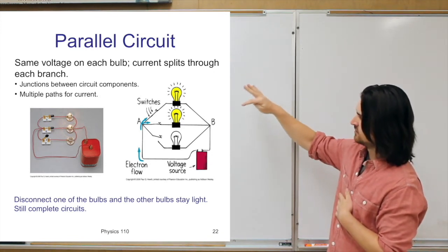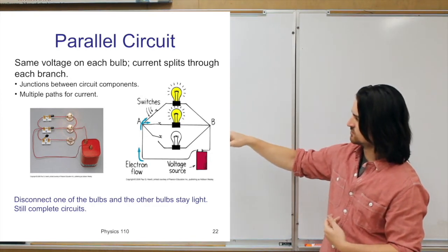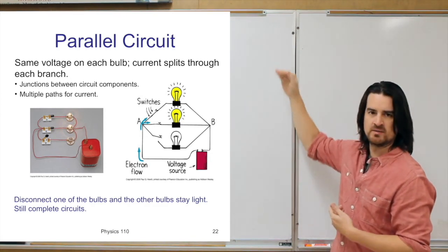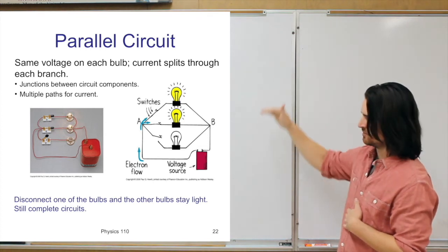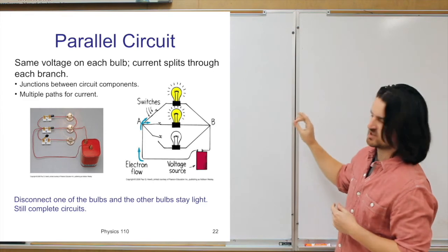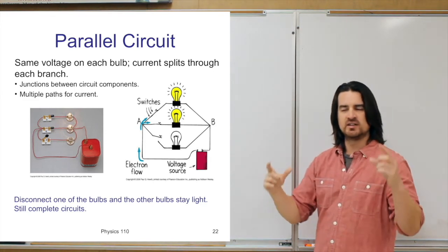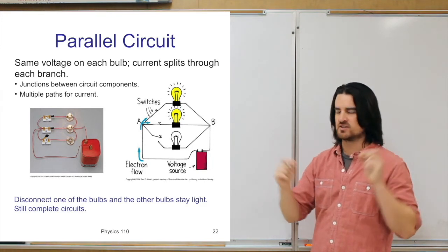But the top and the middle light bulb, we would say, are in parallel with each other. And if that switch was closed, the third light bulb would be in parallel with the two as well. They would all be in parallel. So all of one side's connected together, all of the other sides connected together. So you take any components, like light bulbs, and you connect each of their sides together.